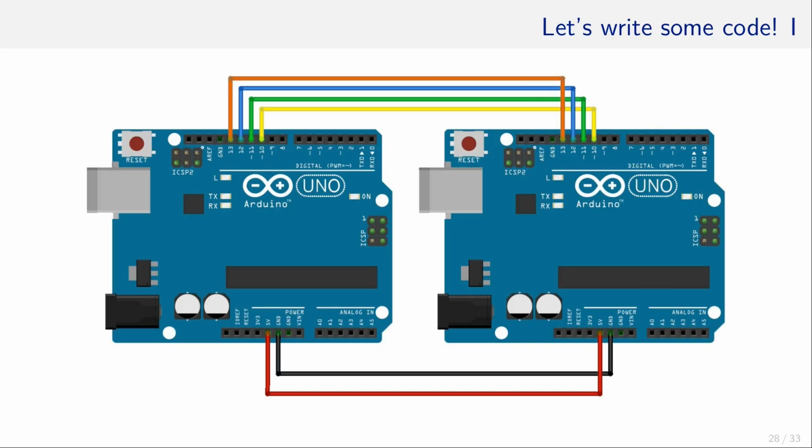The task is to make an additional LED blink that is connected to the Arduino that plays the role of the SPI slave device. In the session, I am connecting the LED to A0 or PC0. Just like that. You can choose any other pin that you like for this exercise, except maybe pin D0 and D1, which is connected to UART, to prevent interference with the programming of the Arduino.